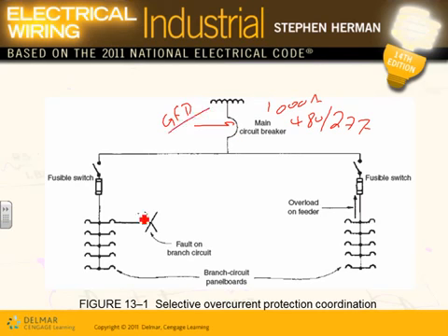So if I have a ground fault right in here on this system, anywhere in this system, that could be sensed and trip the circuit breaker on ground fault. So when I was your age, guys, and we talked about ground fault, it confused the crap out of me. The reason why ground fault and short circuit, you take phase A to the ground, right? Or phase A to the ground, that's a ground fault, right? What's the difference between ground fault and short circuit? Short circuit is phase to phase to phase, that's short circuit, or phase to phase. Ground fault, any phase to the ground is a ground fault.